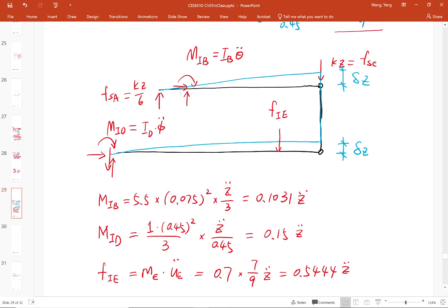This is a force system that should be in equilibrium, and we're looking at all those forces and moments applied on the entire system. So the force inside the link CF is internal, and that's the beauty of this virtual work method. We don't need to be concerned with it.